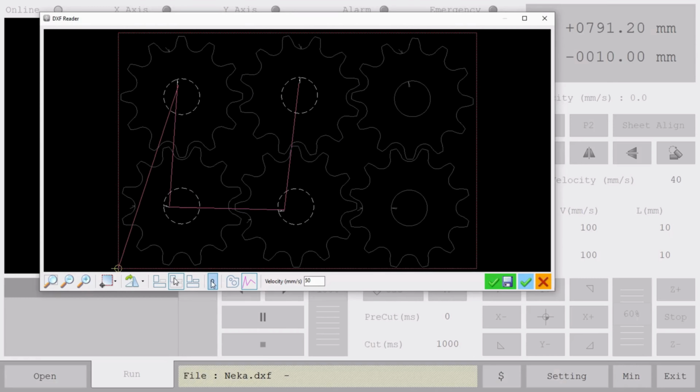The Optimize key, this O that's labeled Optimize right here, actually determines the sequence and the cutting pattern of the parts in such a manner that the machine performs with the absolute minimum displacement. Now, if you observe carefully, you will notice that initially it plans to cut this specific segment, then this one, and then the next. However, once we press the Optimize button, you will clearly see that the system intelligently selects the shortest possible path to the very first segment, then proceeds to the subsequent piece and continues this pattern, ultimately ensuring the absolute minimum travel distance for the entire operation.